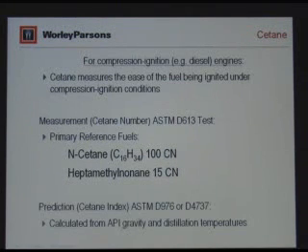Now, so much for gasoline. For diesel, the equivalent of octane is cetane. And again, California has regulations on cetanes and the requirements. Cetane is basically for compression ignition engines. So you compress the fuel and heat it up, and you don't have a spark, but you just ignite from compression.